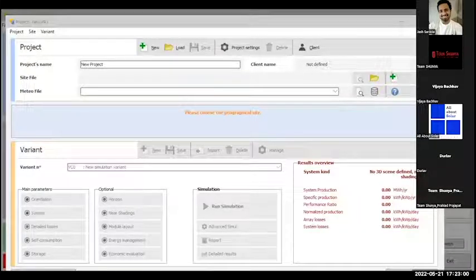You can see with this drawing, it's a project in Delhi, in Chhatarpur RSS. With this particular project, we are trying to create a PVSyst report. We have already done the survey and put the modules here. So we know a certain number of modules can be placed here, and the capacity possible for this particular area is 46.44, where the PV module capacity is 540 watt peak. With this, I'll consider all the parameters.